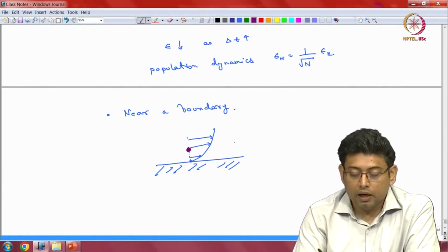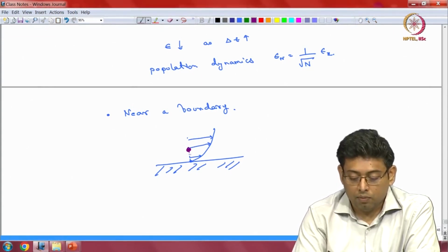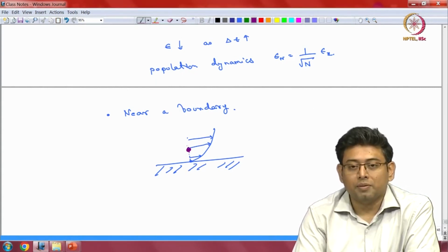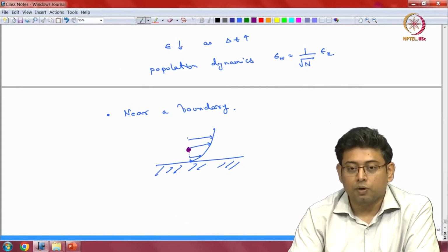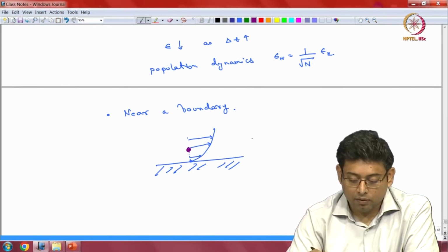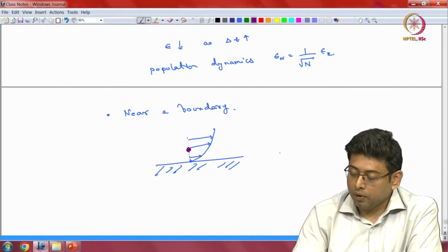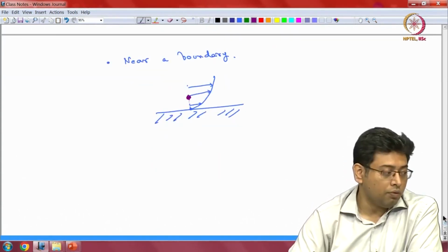Because of that you can have motion of the particle away or towards the wall. Most of the time it's away from the wall. In fact, if you are having flow in a microchannel, people usually use this to focus the particle along the center line of the flow field. So this is one more reason by which particles may not follow streamlines, the local flow velocity.